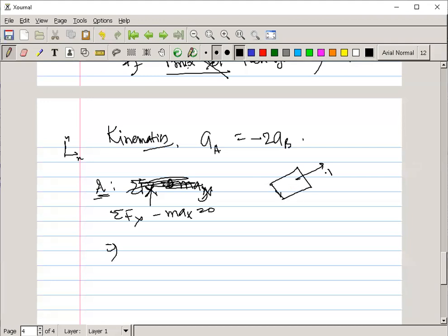So now please put that one. This is your diagram where the tension is already discussed. This is your acceleration. This is your normal direction. So we can write T plus 0.2, because 0.2 is the coefficient of friction, times 588.6 cos 30 minus 588.6 sin 30.